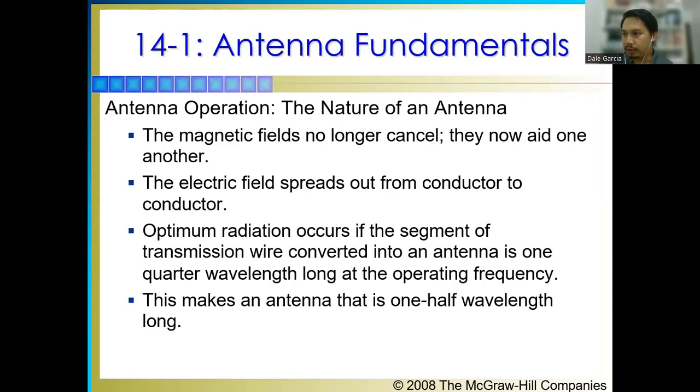For 5G communications and future wireless communication after 5G, we expect signals at around 100 gigahertz. At 100 gigahertz, a very small antenna is needed. A quarter wavelength is 0.75 millimeters. So we can probably fabricate antennas in IC form. Actually, nowadays there are antennas that come in an IC package.